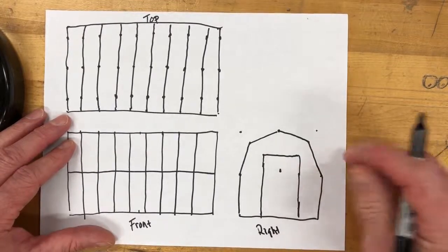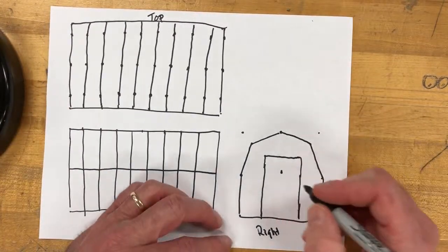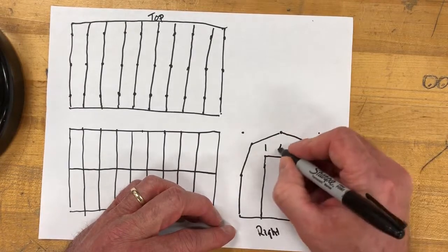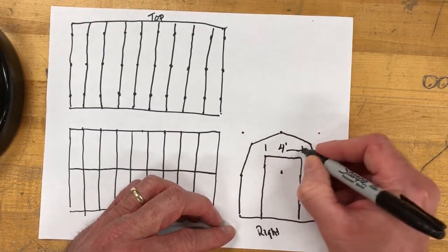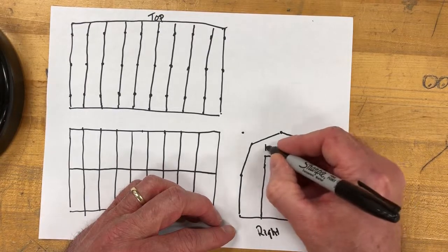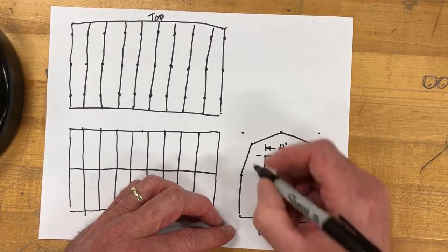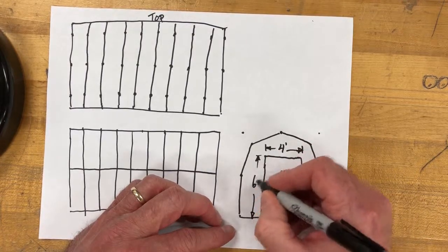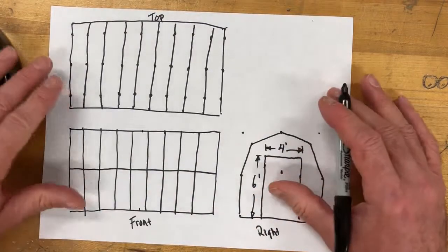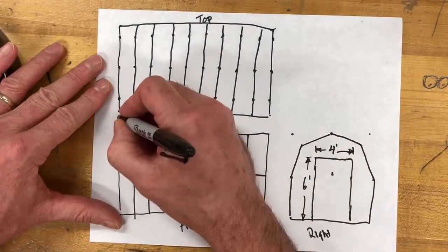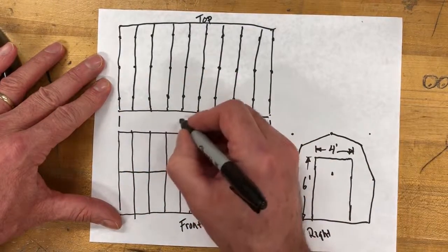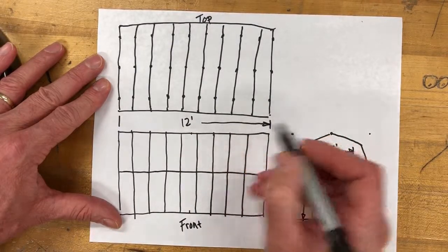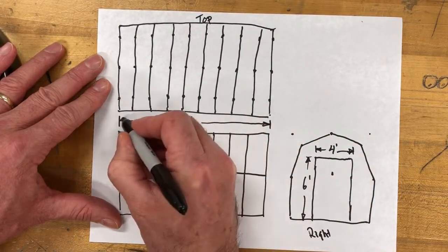And so now I'm going to start dimensioning this thing up. Now the doorway we said was 4 foot by 6 foot. So I'm going to put in a dimension here, 4 feet, with extension and dimension lines, just like we always do. And then I'm going to put the height of the door here. I'm going to set it at 6 feet. And then I'm going to put the overall dimensions in here. So a couple of extension lines. I'm going to make this 12 feet long. I'm going to draw my arrows out here so they're touching the extension lines.